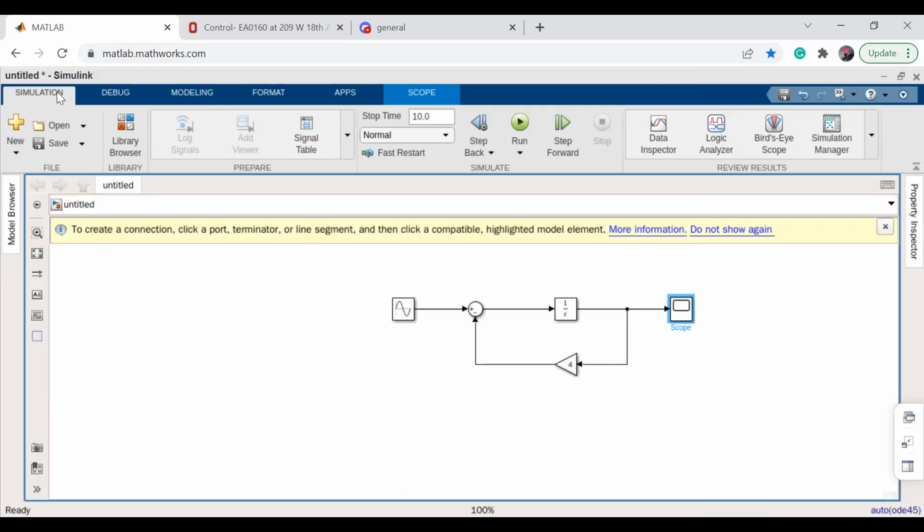And what I want you to do is to go to one of the examples we solved on either Monday or Friday and build the transfer function of that system with the control you had. You had K, so you give K values and then plot and see the response. You're not designing any controller yet. You're just building a more complex model. And I want you to use the step function and run and see, right?